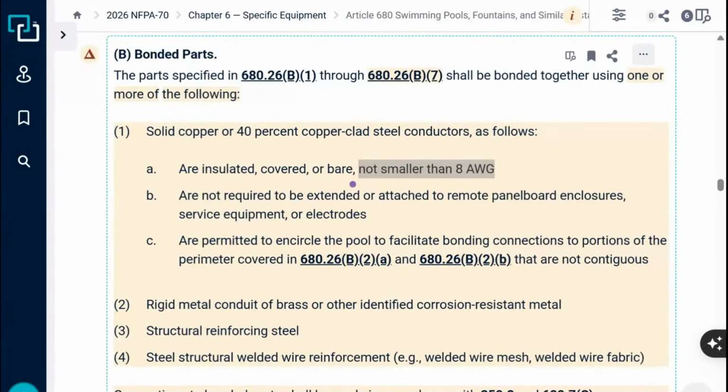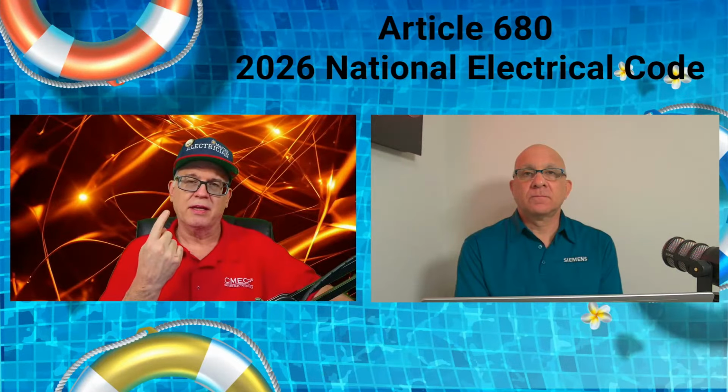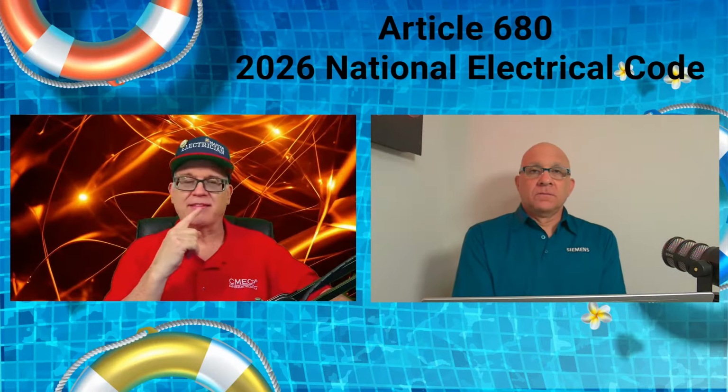All right. And then of course the third one here: they are permitted to encircle the pool to facilitate bonding connections to portions of the perimeter covered in 680.26(B)(2)(a) and 680.26(B)(2)(b) that are not contiguous. In this case, I don't want people to get confused and think this has anything to do with encircling, the old 8 gauge single conductor that can run around. That's not what this is talking about.